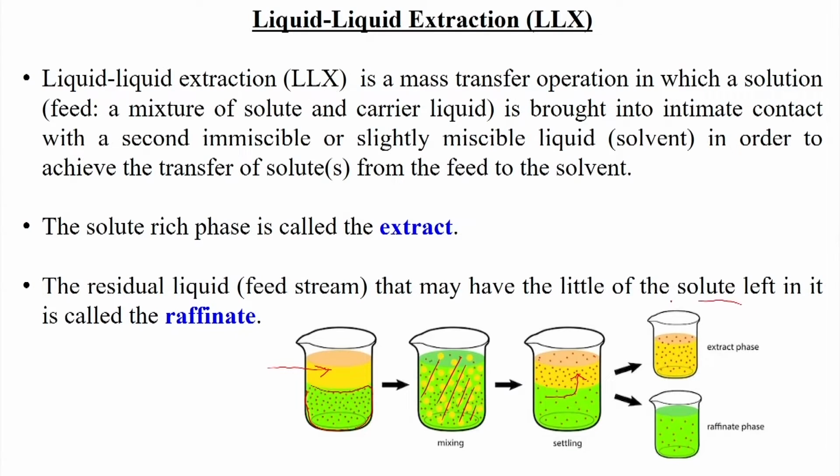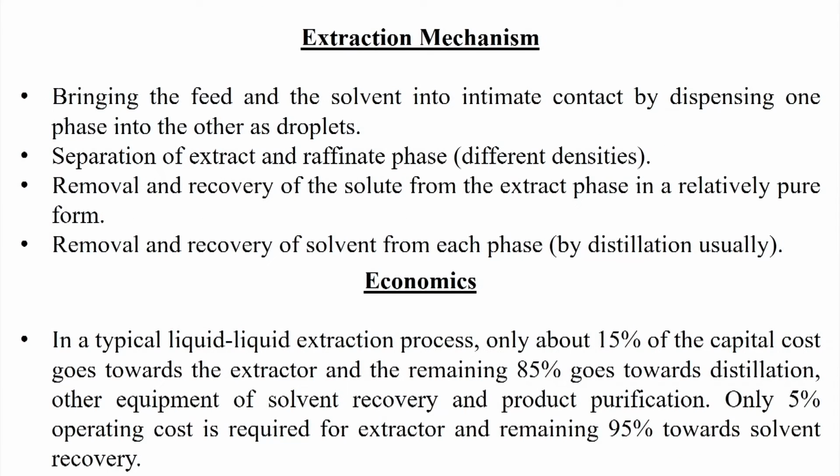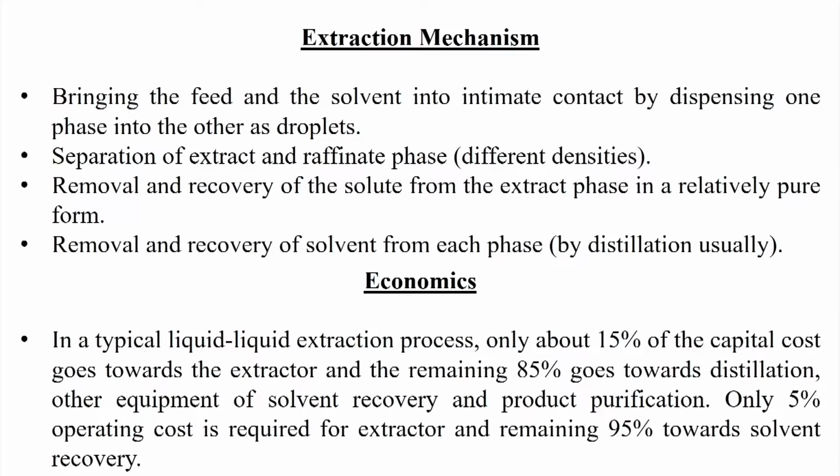This one is rich in the solute, that is the extract phase, and the raffinate means the exhaust phase, where a small amount of the solute will be present. Now, this extraction mechanism is very simple. Firstly we need to bring the feed and the extracting solvent into intimate contact by dispersing one phase into the other as droplets.